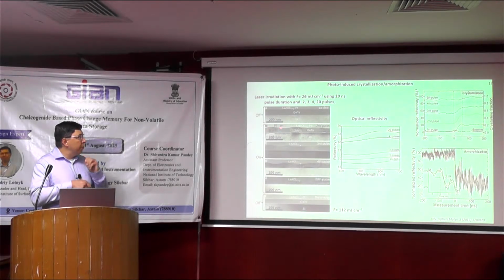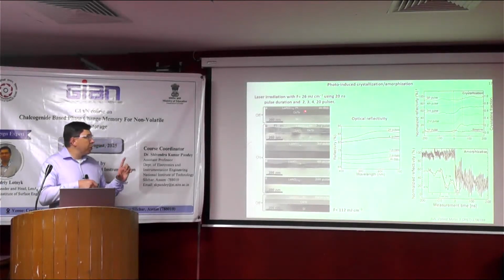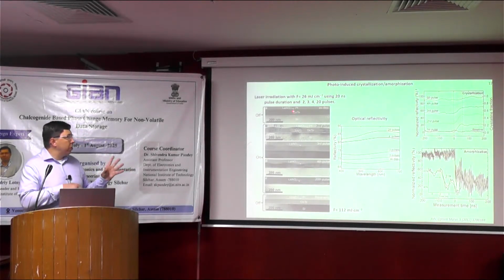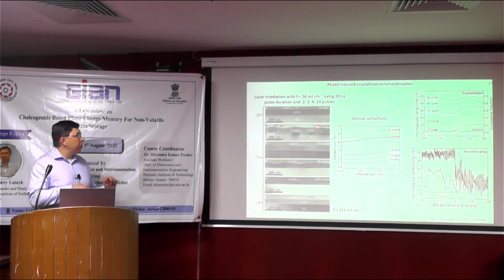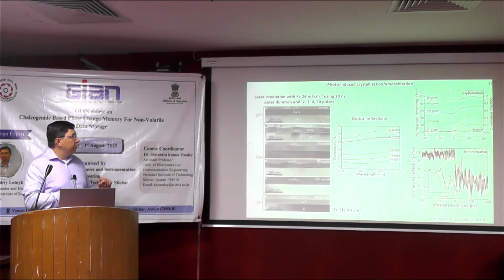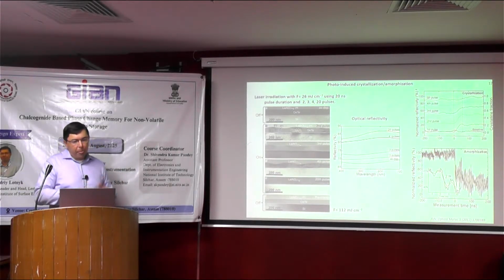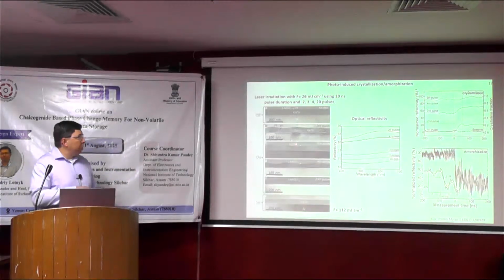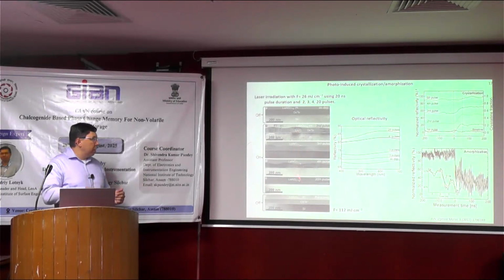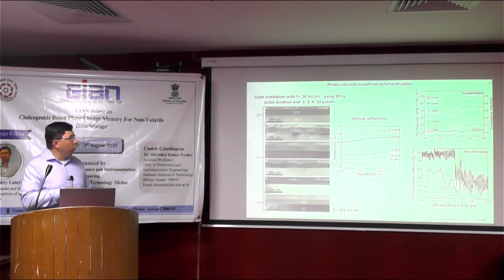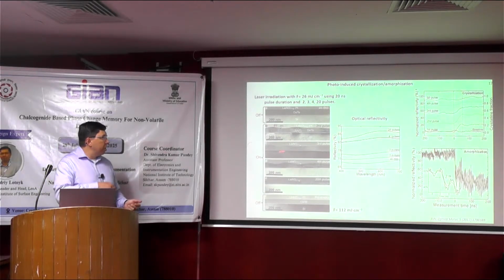Here you can recognize many problems with undoped phase change materials. So first, there is a volume change up to 10% in the case of germanium telluride, and if it's changing, you can get a high roughness of your material. If you want to use it in a device, it's not good because of contacts. You can lose maybe some contacts after several switchings. So you need maybe to dope the material to reduce this roughness of the thin film.